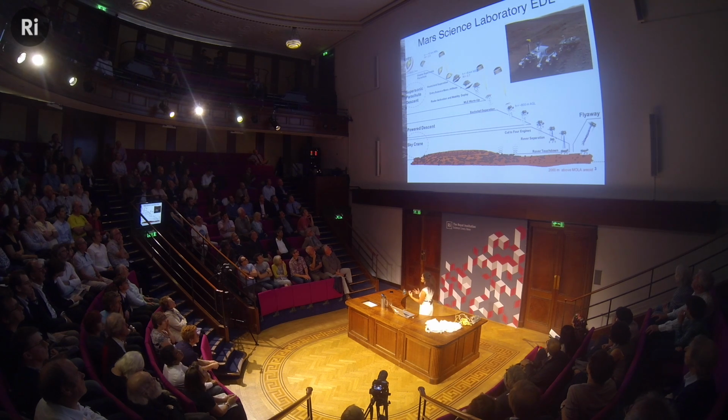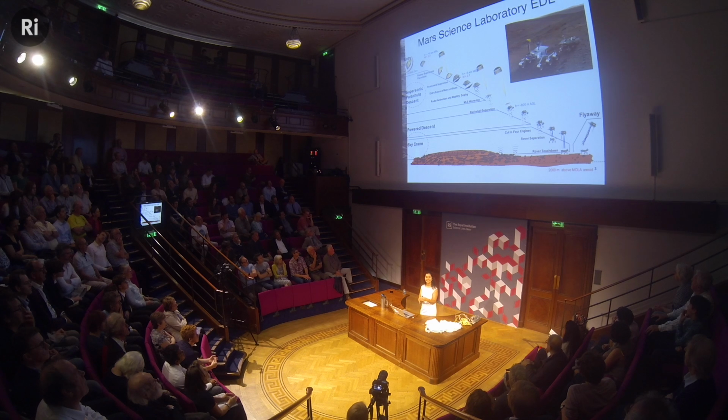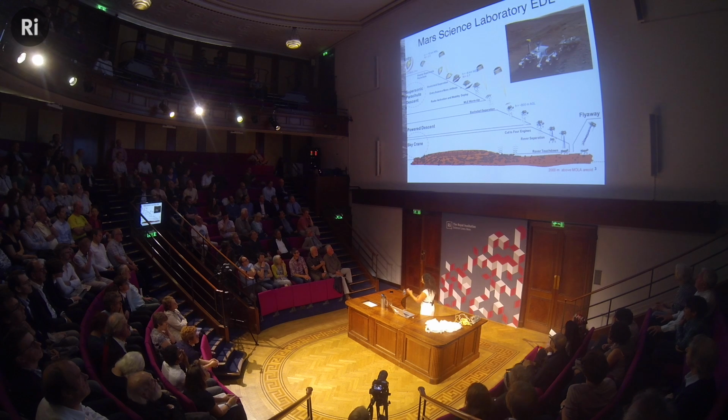And through all this, we have to manage our speed, manage our location, manage our altitude, and we have to know that. And we don't fly this back from Earth because the time delay between Earth and Mars is roughly 14 minutes in the worst case scenario. So this is all done autonomously by the spacecraft, by having knowledge of what the atmospheric properties are, and then making measurements using an accelerometer to tell it basically what its velocity is, and then going through a sequence associated with that. And so this is the overall architecture, and it's broken up into different phases.